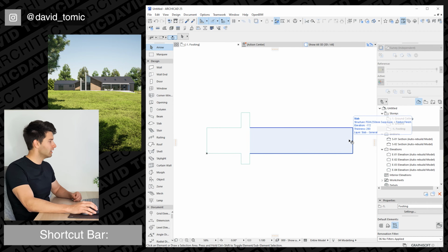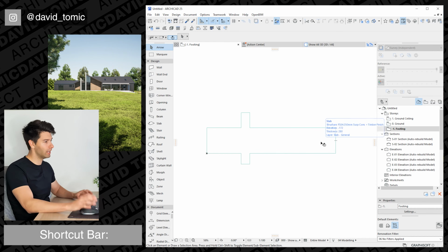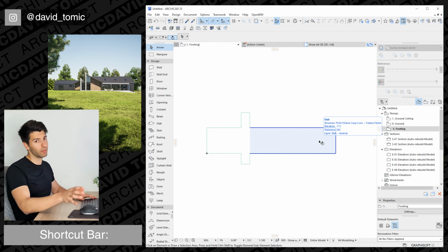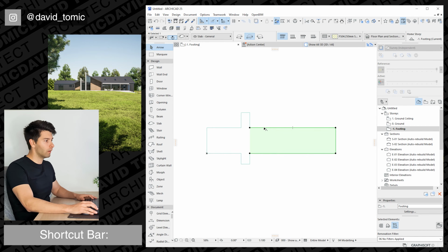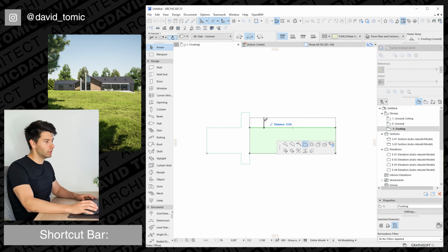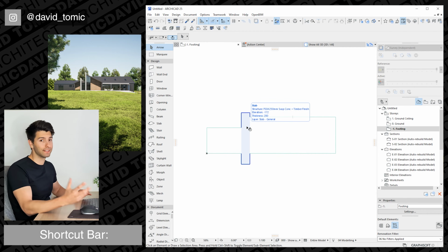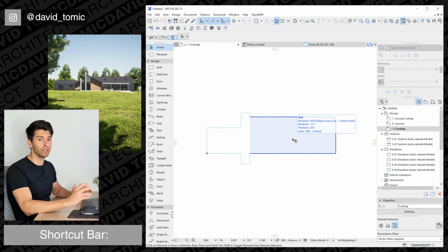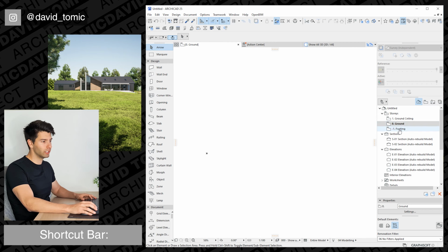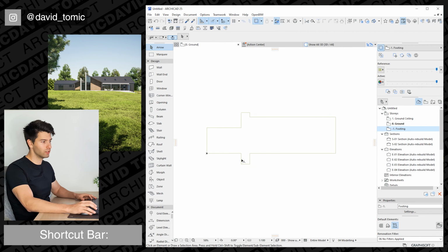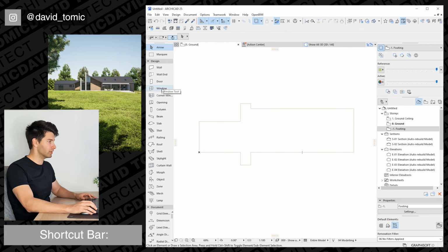That 24 meters is probably a bit of an overkill, so I'm just going to click on it, drag it back 4 meters and call that 20 meters public, 8 meters private with a 2 meter vertical separation in the middle. Now I do know that in real life this extends a little bit further, if not another 2.5 meters that way, but we're not really getting to see too much of that elevation, so it isn't too critical at this point in time. Now if we come up to our ground floor plan by double clicking on ground, right clicking on footings, showing as trace reference, we can see the underside of what we just drew for those slabs.